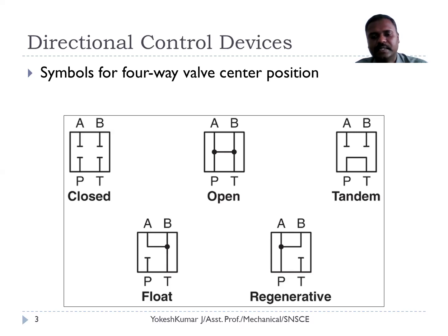And the third is tandem center. In the tandem center, actuator ports A and B are completely closed, and the pump port is connected to the tank port. Whenever there is no actuation in the valve, we don't want to actuate the cylinders. The center position comes into operation. The pump is completely pumping the fluid from the reservoir.